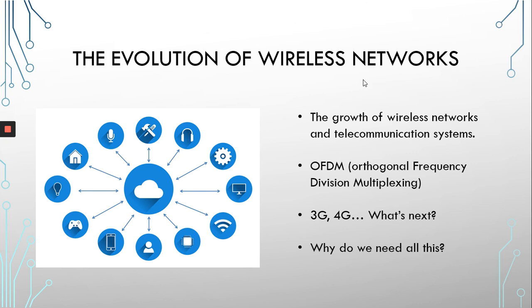During all this improvement, a core technology which actually enabled much of this is OFDM, especially in wireless communication technology, which means orthogonal frequency division multiplexing. This is a multiplexing technique which basically uses the orthogonality between its subcarriers in a symbol. It uses the orthogonality to be able to squeeze in more subcarriers within a given frequency bandwidth while minimizing interference between them. As a matter of fact, there is zero interference between them as they are orthogonal.